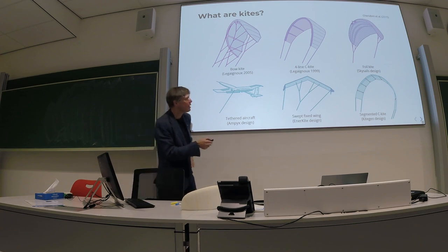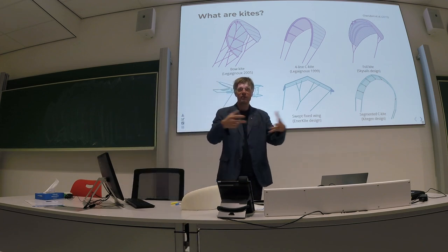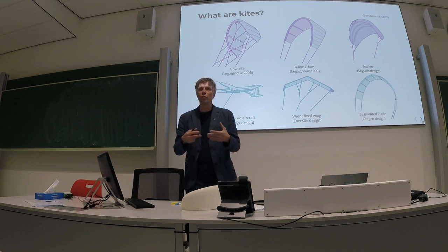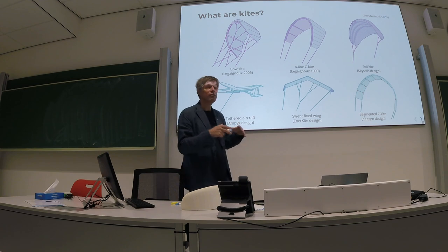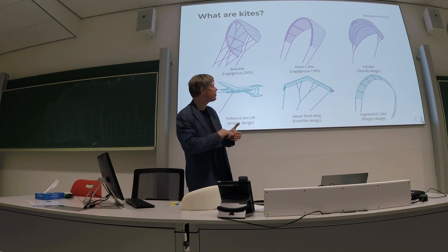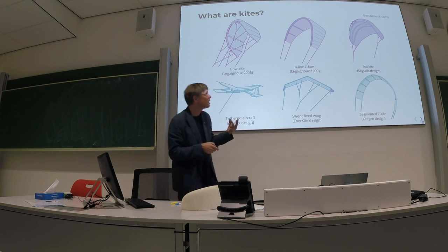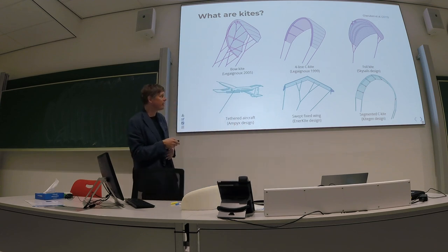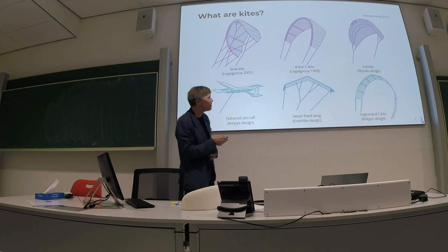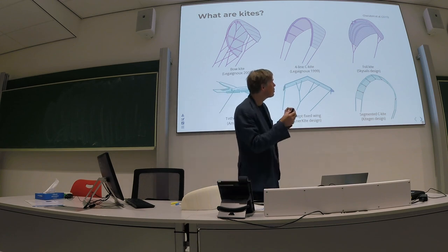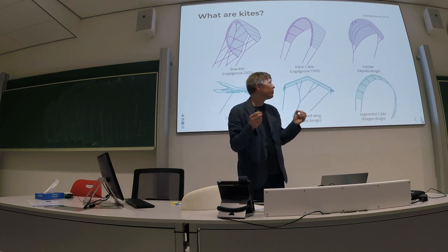A ram air wing is just a piece of cloth without any pre-inflatable elements. You really need to get this thing flying somehow so that the stagnation pressure inflates the wing. Here are the openings for the incoming air for the stagnation pressure to inflate. Sky Sails used this design with only 2 tip tethers because the entire wing was steered by roll control.